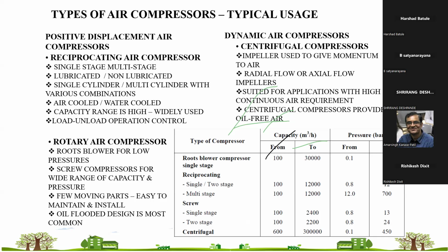Majority of the older industry, or many process industries, use reciprocating air compressors due to the requirement of higher pressure, and because they can be useful for multi-stage or delivering high pressure. The reciprocating compressors are used. Another is your rotary air compressors. Rotary air compressors are further divided into roots blowers and screw compressors.